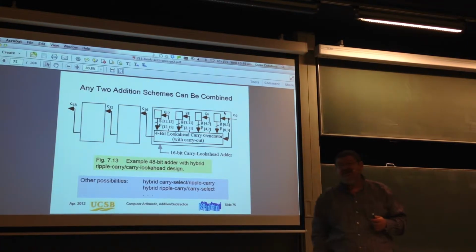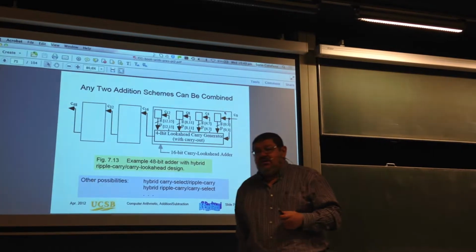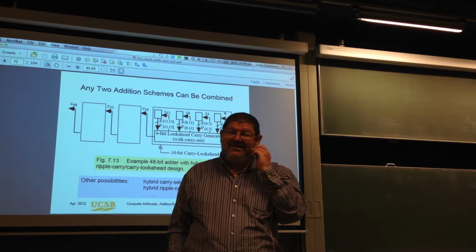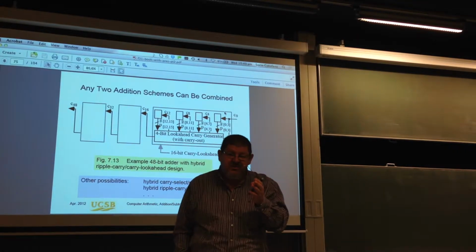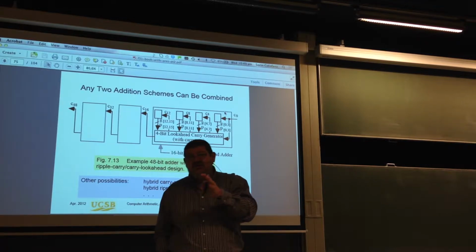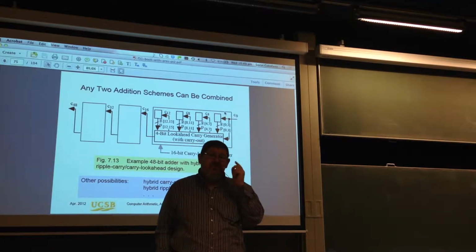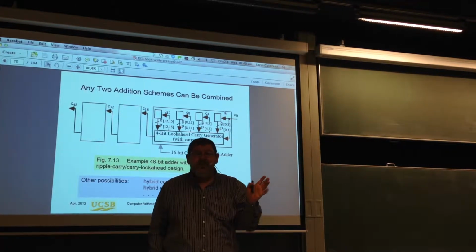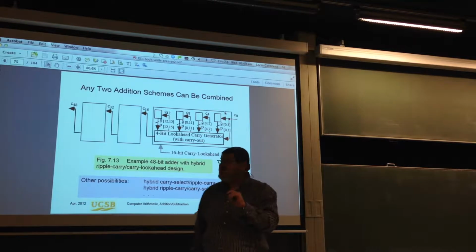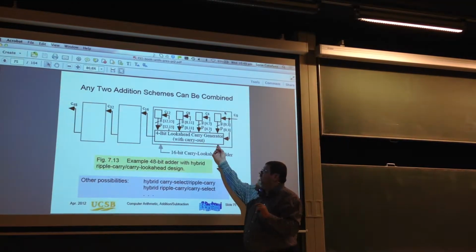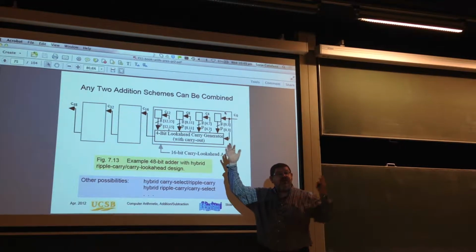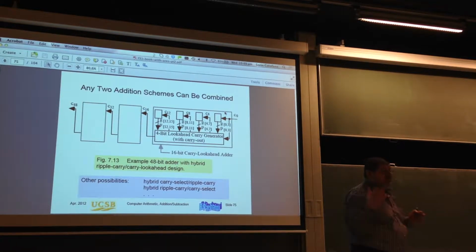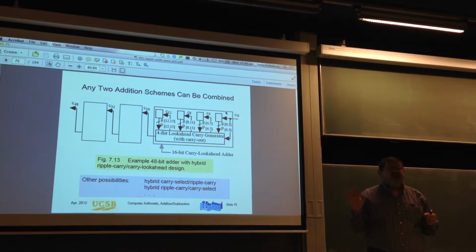Yes. Less circuit. The lesser circuit that I can build, it's a ripple carry adder, so less cost to performance trade-off. Then it's a trade-off between cost and performance, because now I ripple over look-ahead adders and not over full adders. But there is something else in it, because this is not very deep. It will not have that much energy consumption. I will not go too much down and return. But those kinds of things you have to consider carefully when you make a design.